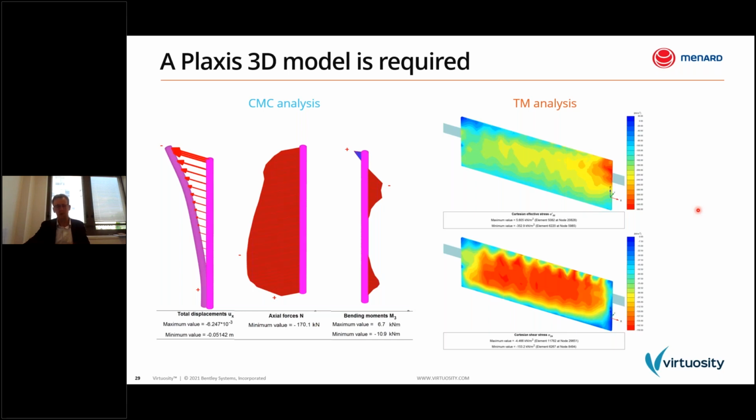But at the end, it's quite easy. We can use this beam to plot the axial force and the bending moment, and we just need to multiply the results by the factor of 10 to the power 6 to get the result. So that's a trick, I would say, to easily capture the axial force and the bending moment in volume element just by adding a beam inside. But maybe Richard has other options to do it.